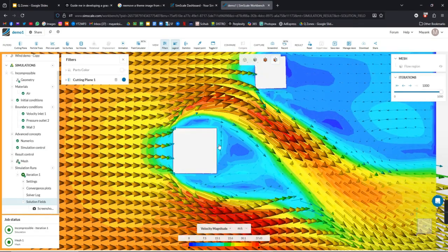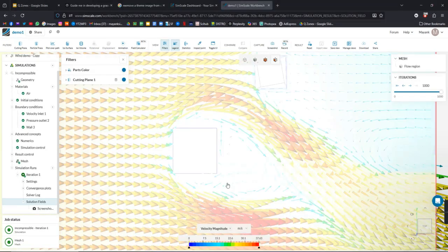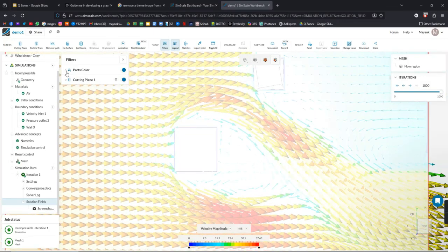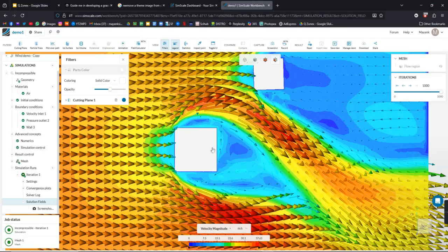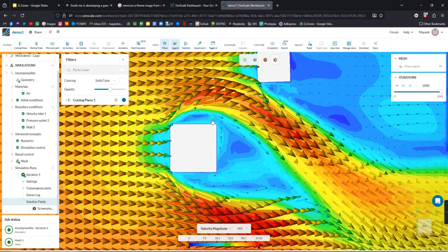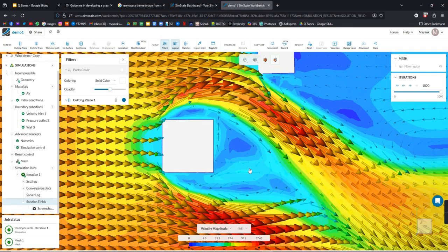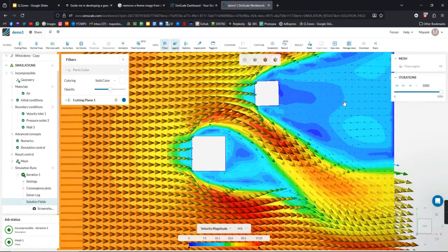right, I can also switch off the color. Yeah, you can switch off the color, but it's just better to have it something like this. And you can see how these arrows kind of turn around, and they lead to something known as eddies. Basically, it's like this negative pressure zone that has these tiny whirlpools. You can see here wind is in this direction, and that's why these negative eddies are coming up.